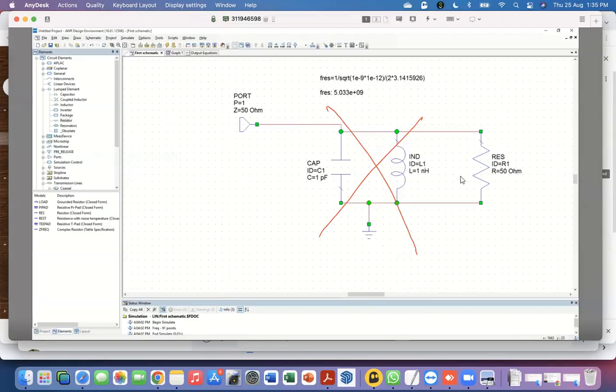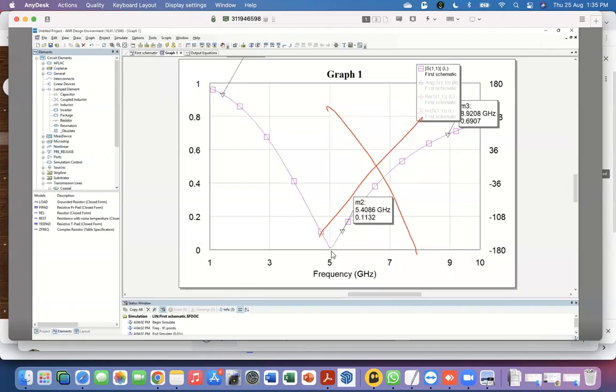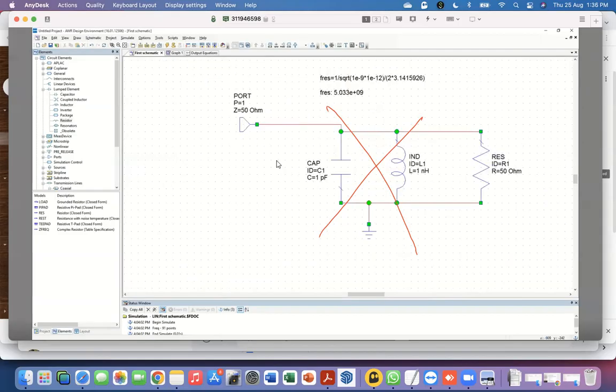So you have maximum power transfer, which means no reflection. And that's why this goes to 0, but exactly only at that particular frequency. At other frequencies, you have reflection because the load is a combination of some reactive part and some resistive part. Okay. And if this was not 50 ohms, here I can introduce another concept of microwaves. So hide this, and we will stop after this, already getting a little late.